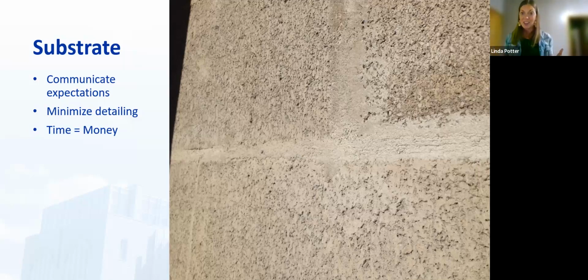And so we have to tell them, when you build your structural wall, we actually want you to float those mortar joints like what a tile setter would do. So that you see what you see here, which is fully flat and minimizing as much of those air pockets as possible, so that this is ready for air barrier to go right on it. Same thing would go for sheathing or anything else that you might be putting your air barrier on. Ensure that they understand what you mean when it's air barrier install ready. Otherwise, there's just too much misunderstanding or miscommunication about what that means.